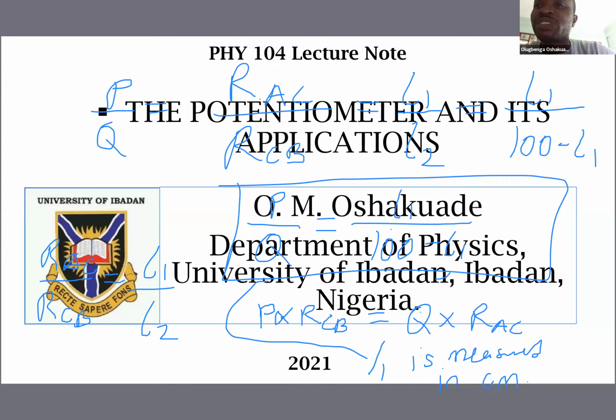There is a question here that says, sir, since the current is moving from left to right, why not VB minus VA, not VA minus VB? VA has a high potential there. That is why I chose to take VA minus VB, because VA is connected directly to the positive terminal of the battery, while VB is midway, all the way towards the negative terminal.